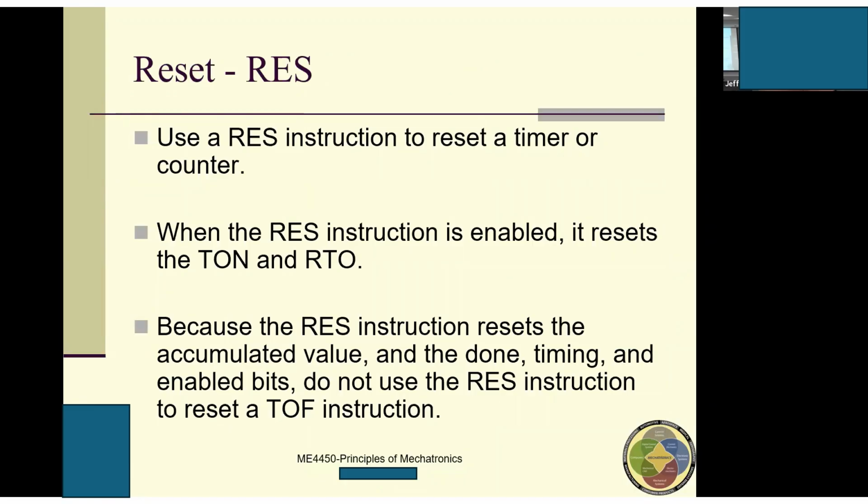So reset. RES is an instruction to reset a timer or counter. We can use RES not only to reset a timer, but also to reset a counter. The counter will be talked about this upcoming Monday. We talk about timer first, and then we'll talk about counter. Timer and counter can be used together to do a lot of fun things. So when the RES instruction is enabled, it resets the TON and RTO.